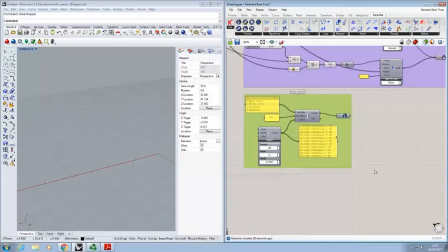And later on, we're going to run the optimizer, which would basically loop through the entire list of cross-sections and choose one for each element, which will give us a utilization of 100% within a deflection limit that we're going to set. So the only thing now left before we can start running this analysis is the material setup.